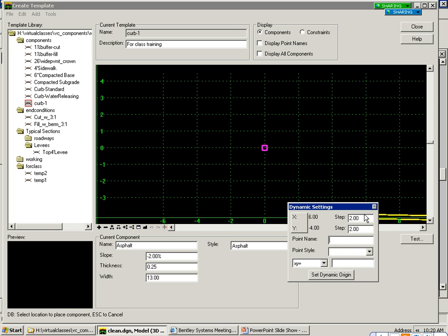So what I'm going to do is I'm going to back this off, and I'm going to make it a 0.2 and a 0.2. Okay? And what this is, over here, it's XY step, or it's X, meaning this back and forth, and slope. So you can lock the slope down so that it's a series, just like our vertical design tools, actually. I'm going to set that at 2%, just a second here. And then what will happen as I change values, then it's going to be locked down to step in the 2% range. But I'm going to put this actually back to an XY with a 0.2.